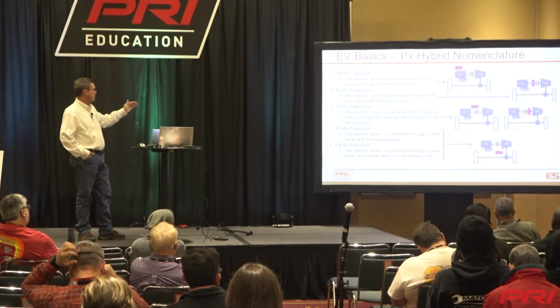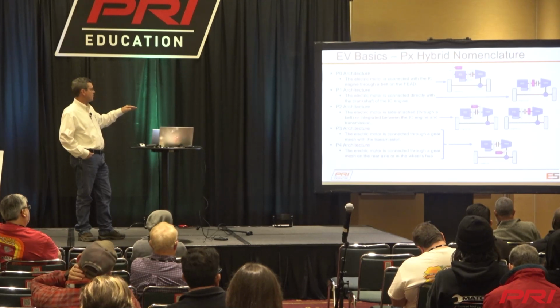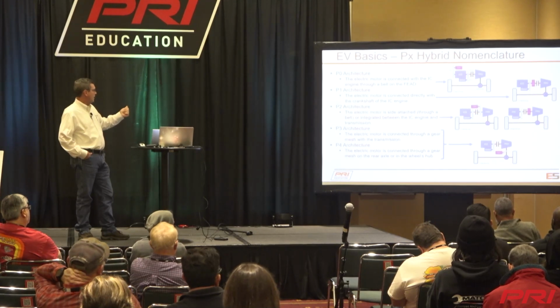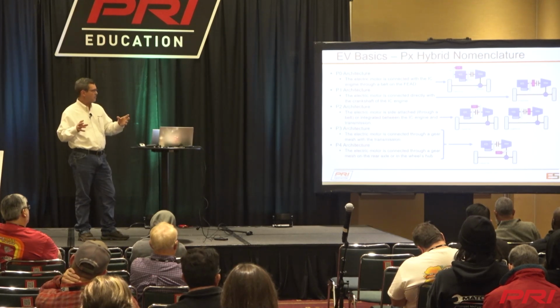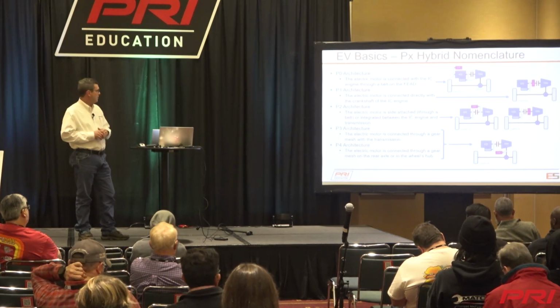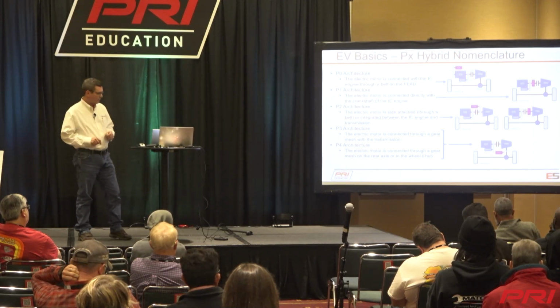The P3 architecture or P4 architecture, the electric motor is after the transmission, and it's connected through a gear mesh. If you see wheel-mounted electric motors or axle-mounted electric motors, that would be in the P3 or P4 class.